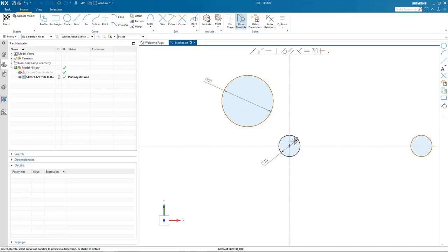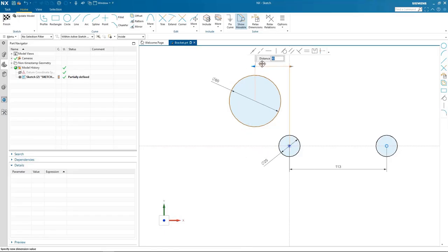As you can see here, the brown curves are still movable. So what I need to do is start to lock those two down. What I do is simply add dimensions to fully define where these circles belong in space. It is as simple as picking and adding dimensions and typing in the values that I need to control where these circles go.